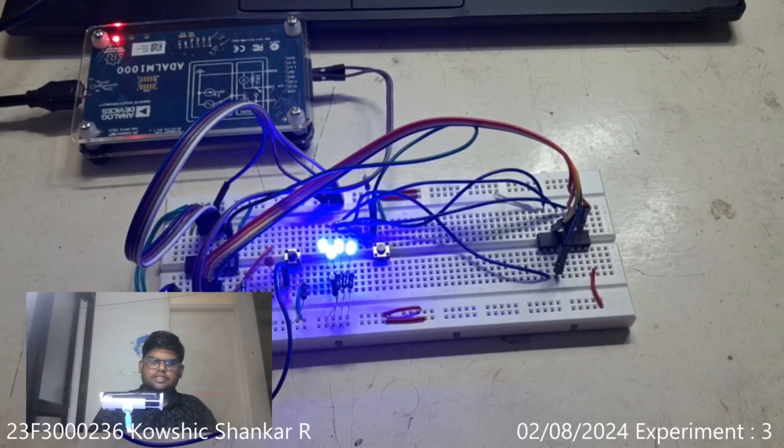As you can see, the initial value is 15 rather than 0, because without the ripple carry being high, it is the zeroth state from the counter IC, but after feeding through the NOT gate it becomes 15.